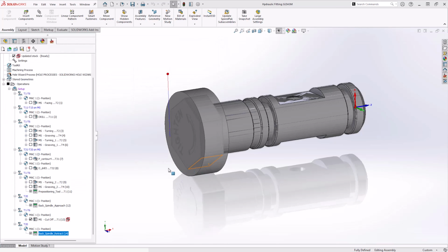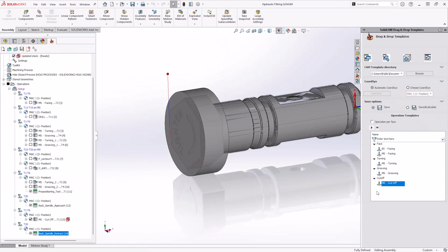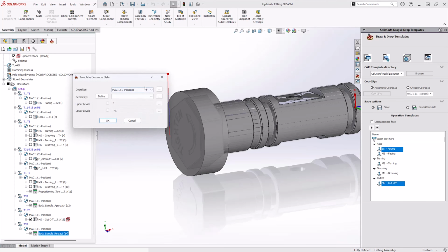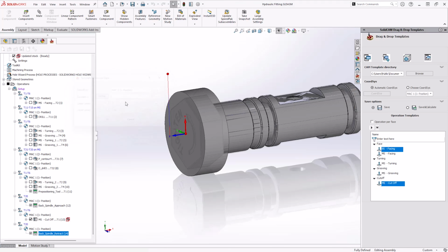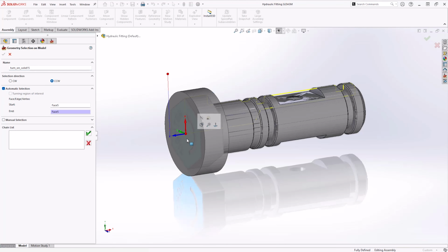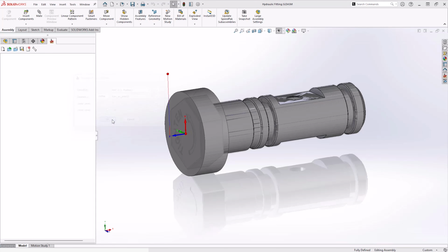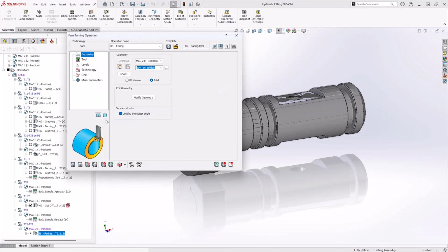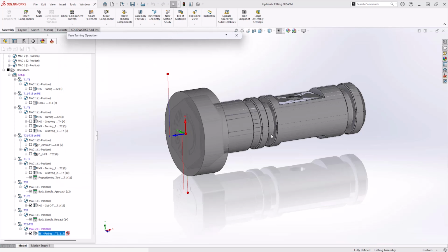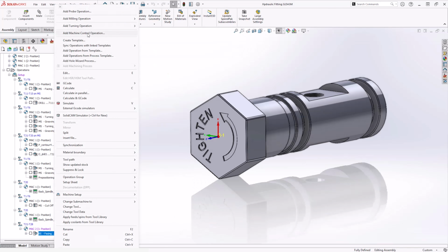This goes and puts the machine in a position where we can start using the Y2 tools to use for the facing, which we can take from a template yet again. We can also in that template choose a new coordinate system, Mach 2 in this case, pick the face, and then it'll do the rest for us, even changing the tool to X- because that's what's required because of where the tool sat in the machine in this instance.